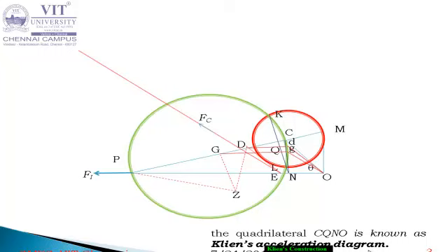How can you calculate it? Inertia force is equal to m r omega squared. Here m is the mass of the connecting rod, r is the radius of the crank, and omega squared is with respect to the crank rotation. By using this equation you can find the inertia force. Only the mass component differs; the mass of the connecting rod we have to substitute.